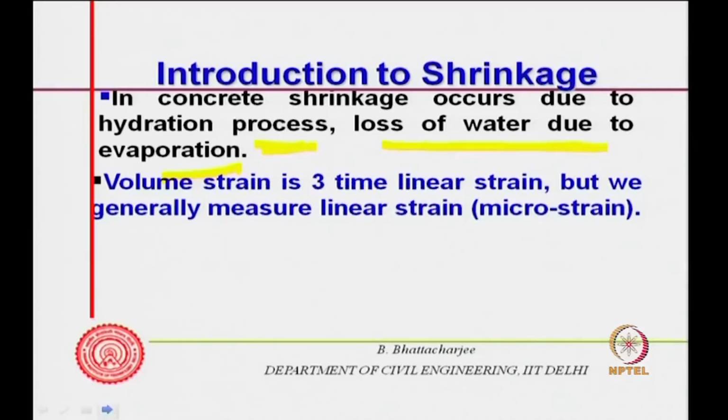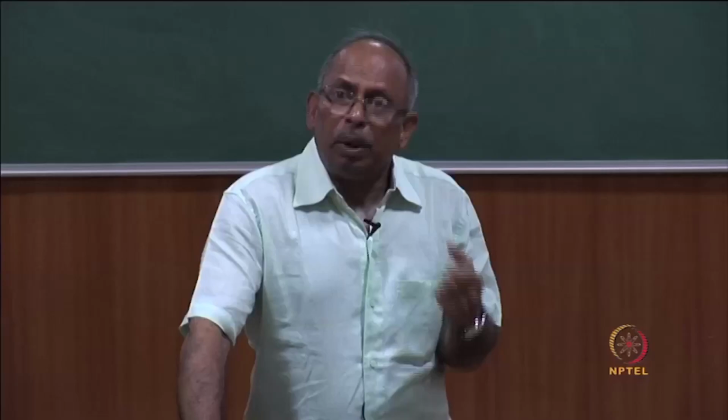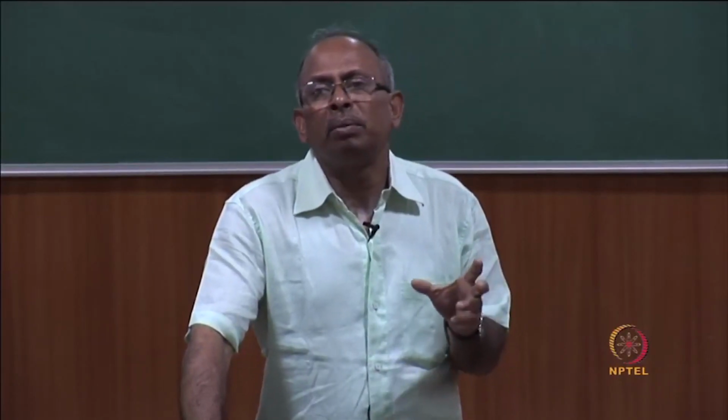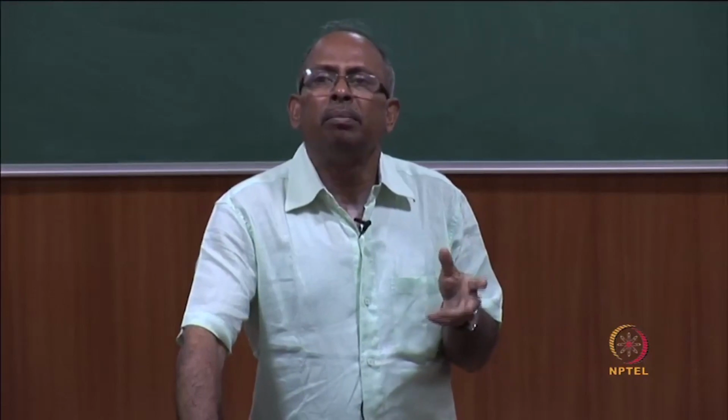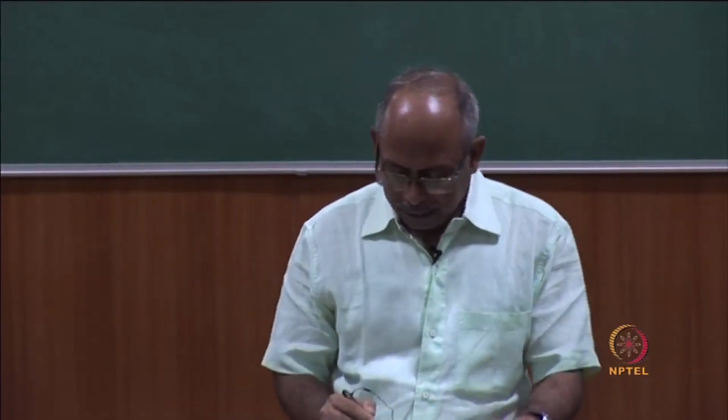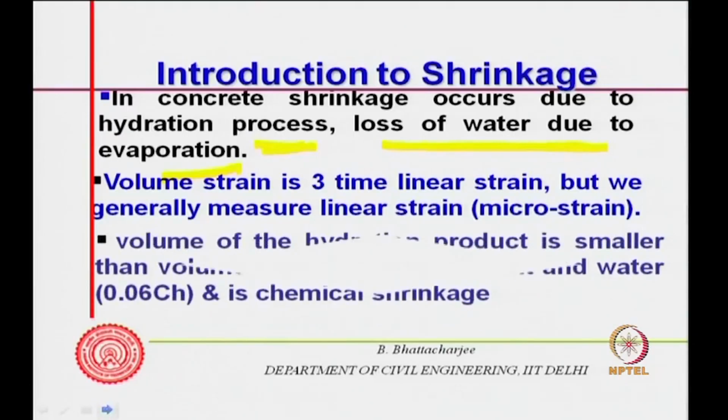So, generally there is a volume strain, it is not actually linear strain, it is essentially volume strain, volumetric changes are occurring. But we measure the linear strain, and the shrinkage, when we talk in terms of linear strain, is in microstrain, order of 10 to the power minus 6. So, we measure it that way.